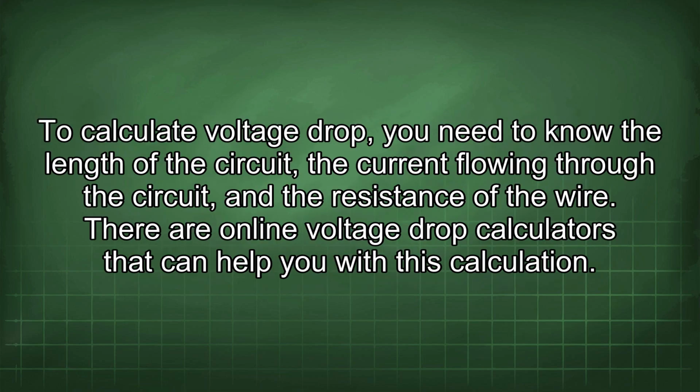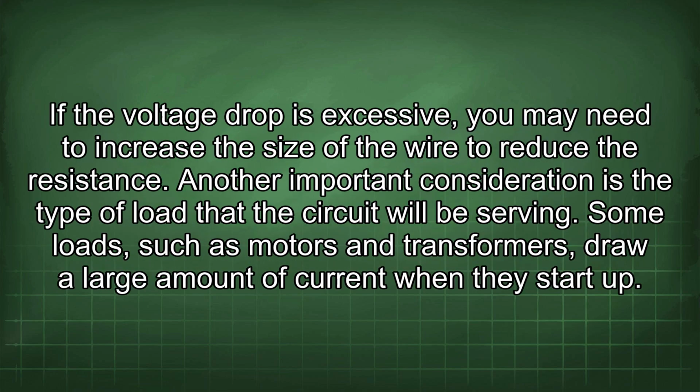To calculate voltage drop, you need to know the length of the circuit, the current flowing through the circuit, and the resistance of the wire. There are online voltage drop calculators that can help you with this calculation. If the voltage drop is excessive, you may need to increase the size of the wire to reduce the resistance.